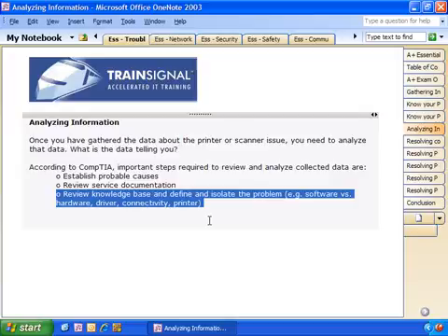And it was just the form. The forms were kind of at an arch, and if you laid the forms on a flat table, you would kind of see a little bend right there at the end of the form, and that was what was causing the jam. So the paper was intact. It wasn't frayed. It wasn't cut in half or torn or anything. It just had a little arch near the end of it that caused the printer to jam. Nothing wrong with the printer at all. So you have to really try to isolate these problems and examine everything that's going on. Printers are very complex mechanical devices.